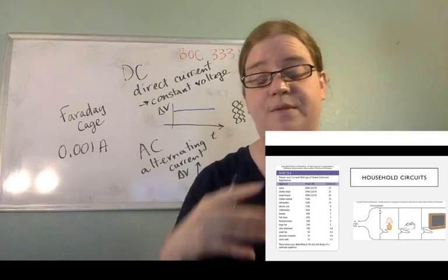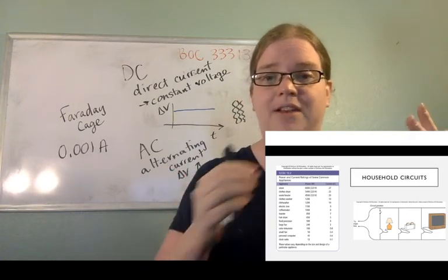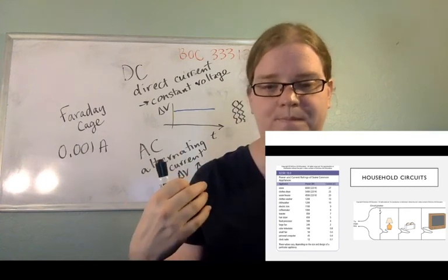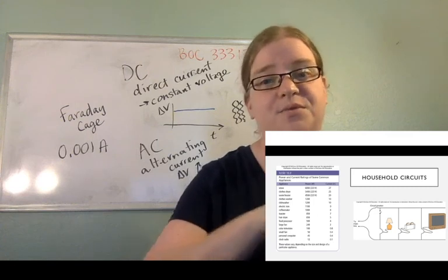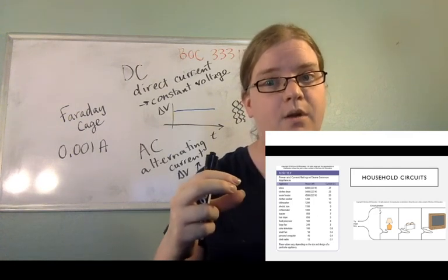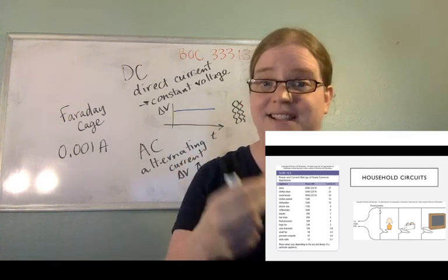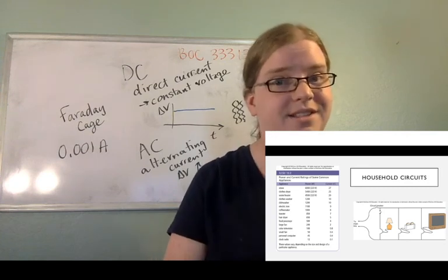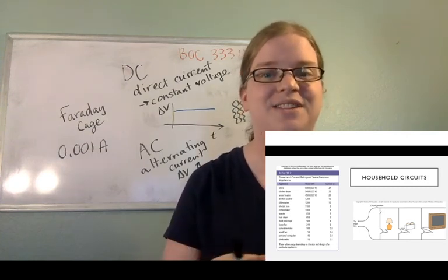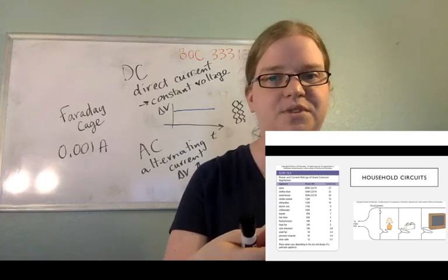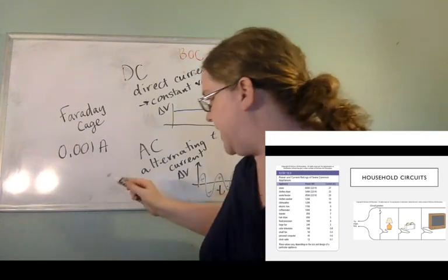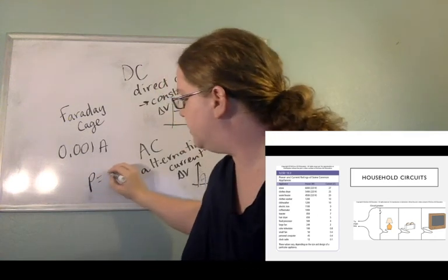But in any case, you've got your voltage source and you draw more and more current from it. And as you draw more current from it, you're more and more likely that those wires get heated up, okay? And that's how you can start fires with electricity, when the elements draw too much current and they heat up too much, right? Because the power dissipated depends on current squared.